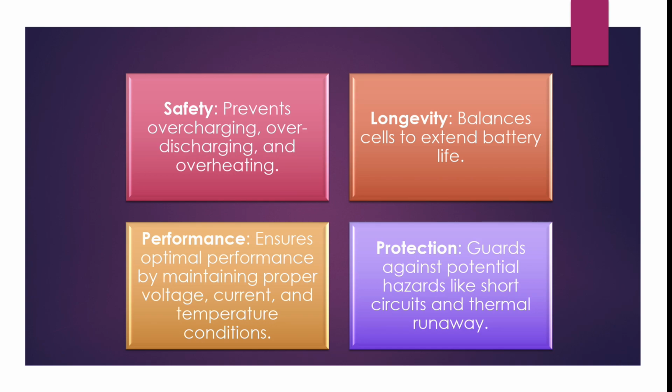Safety: prevents overcharging, overdischarging, and overheating. Longevity: balances cells to extend battery life. Performance: ensures optimal performance by maintaining proper voltage, current, and temperature conditions. Protection: guards against potential hazards like short circuit and thermal runaway.